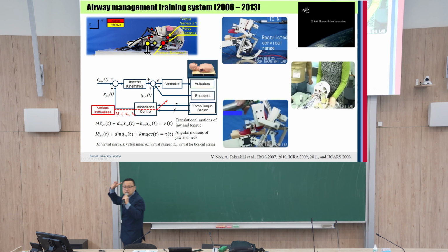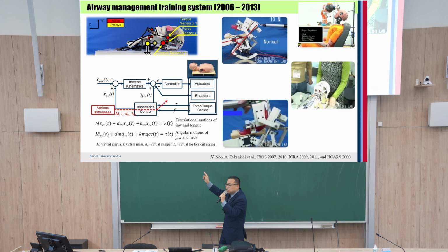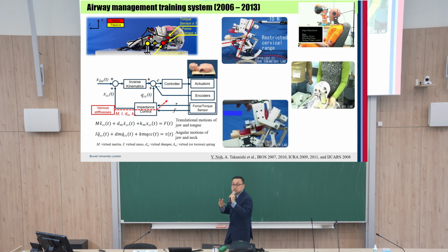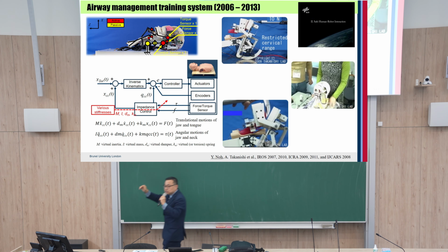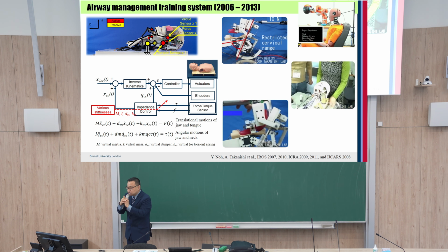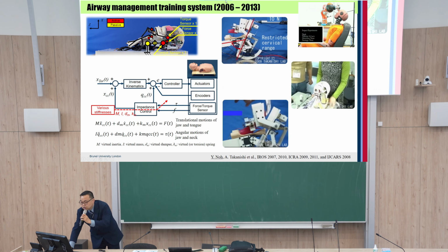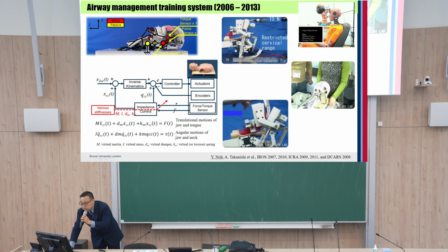Force and torque sensors are integrated into every joint of this patient robot, and impedance control, which can make all the robot joints softer, is embedded into it. So see here, when we apply a force of 10 newtons, the neck rotates 10 degrees, and in the second case, 45 degrees.